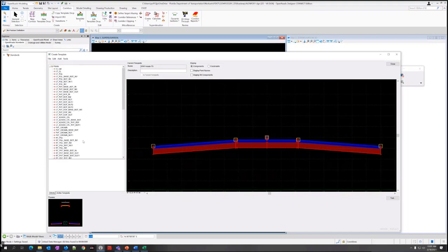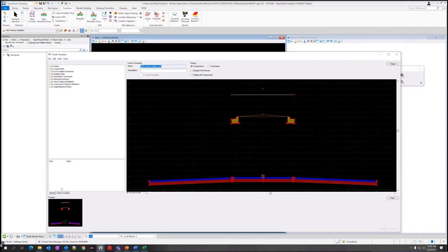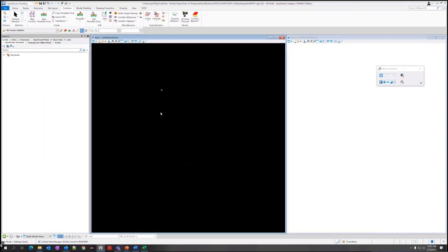If you want, you can check, and exercise 6 says, okay, check the same thing for the median curb template. So if I go over to library, because we have, remember, 2 template drops on that. So you want to make sure all your template drops have the same thing, and this one does. So there's my super elevation points. So I'm going to close that.